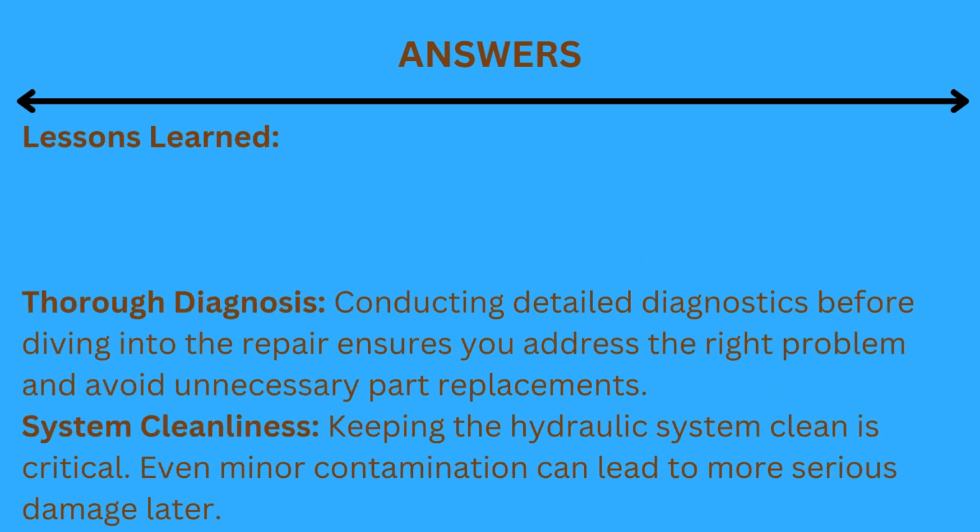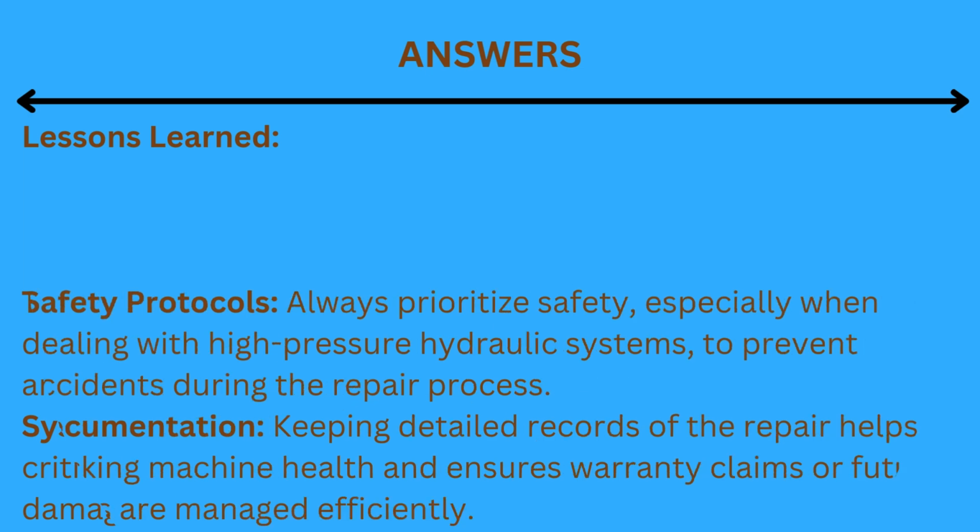Lessons learned. Thorough diagnosis. Conducting detailed diagnostics before diving into the repair ensures you address the right problem and avoid unnecessary part replacements. System cleanliness. Keeping the hydraulic system clean is critical. Even minor contamination can lead to more serious damage later. Safety protocols. Always prioritize safety, especially when dealing with high-pressure hydraulic systems, to prevent accidents during the repair process.